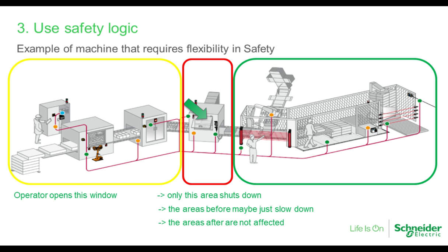So logically, if you were to use a logic flow chart like this one I have here, handling the e-stop is a matter of having the e-stop affect all of those three parts of the machine the same way.